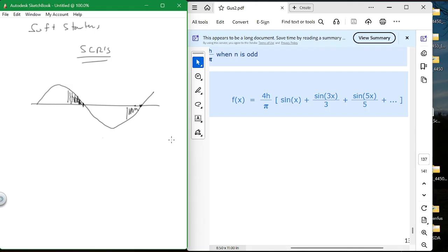So what they wanted to do was go to inverters, because with inverters, you can run them at a slower speed, and then when you get to 400 degrees, you can raise them up to the regular circulating speed, and you're running on 40 horsepower, and you're good to go. So you run 40 horsepower, that's all you need. So what he did was he bought a 40 horsepower soft start, hoping that by the time you got up to full speed, you'd be at 400 degrees. Didn't happen. Wasn't even close. And you couldn't control it. So he had all these soft starts that he bought for this one oven application. He had to take them all back and then put in inverters.